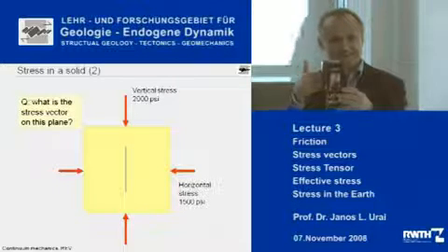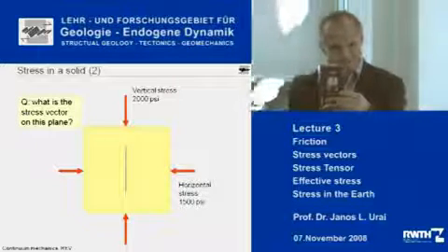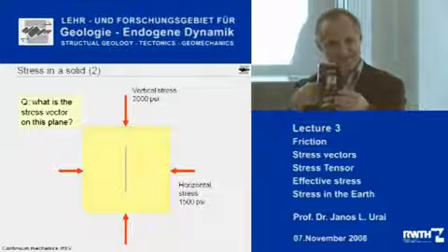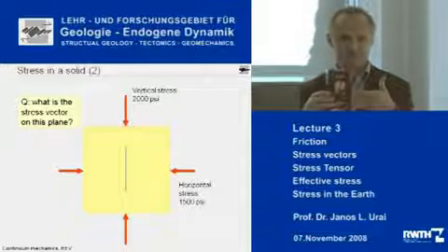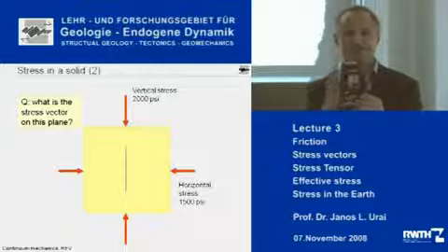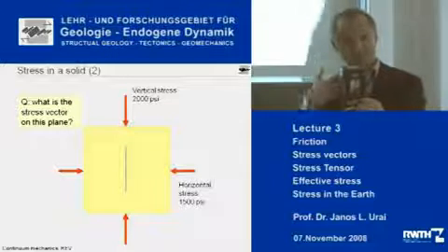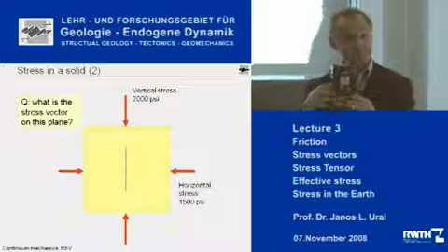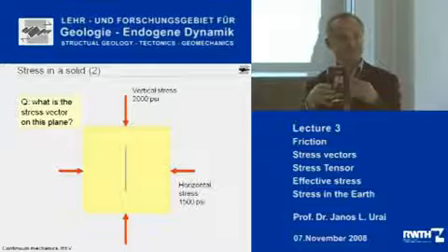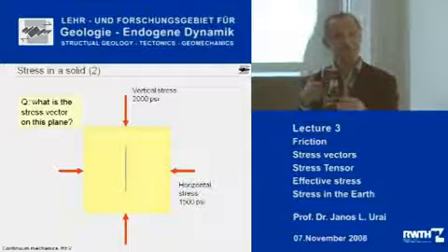Then there is exactly equilibrium with the stress vector on the plane and all the stresses which act in all other directions. So basically, I take away the block which is pushing back and replace it by a stress vector without the other side noticing. That is the stress vector on this plane.